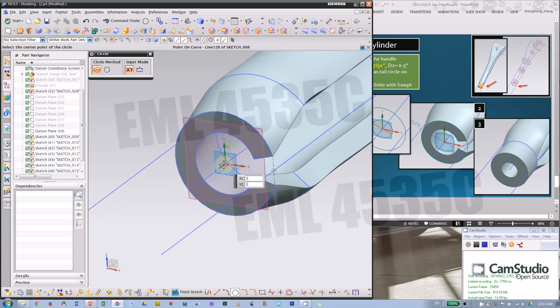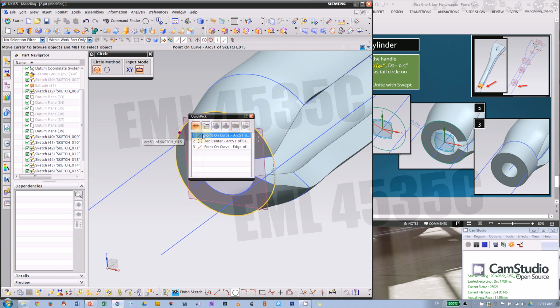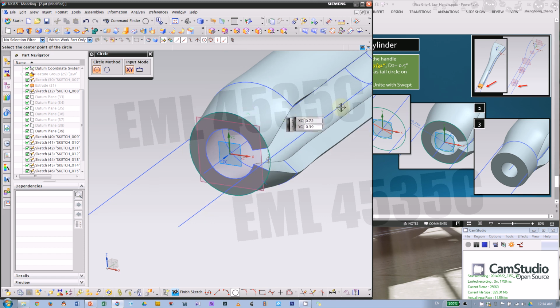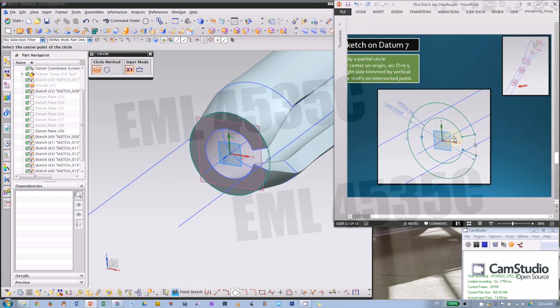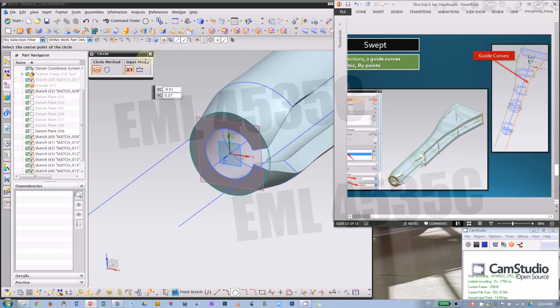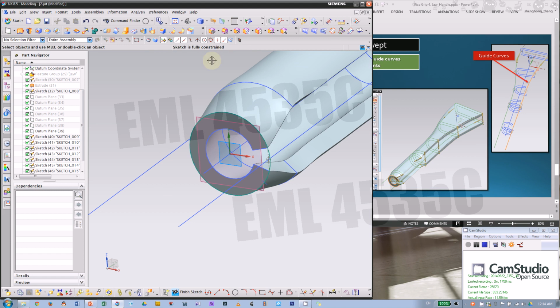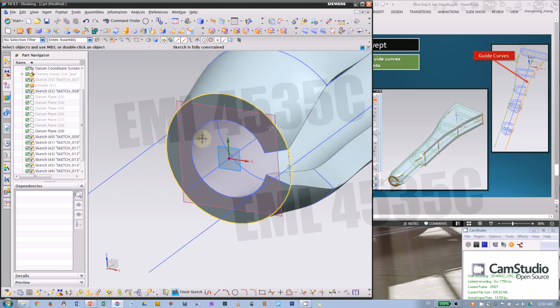So first it's gonna be a circle from the sketch origin to exactly the same as a circle on this section. So you can snap to that sketch. Okay, so that's why you don't need a diameter for this circle.